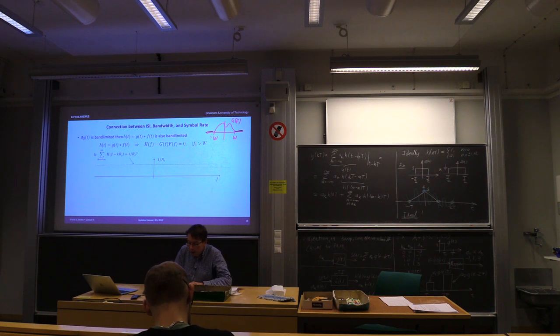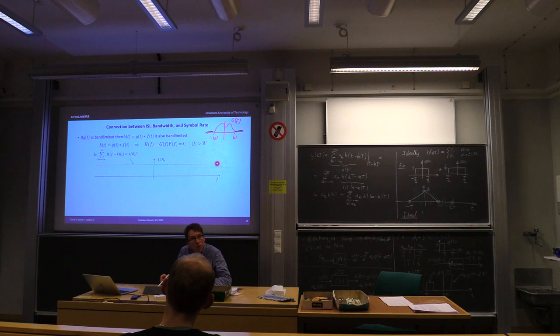So the question we had, to show that H is a Nyquist pulse, is to see whether it fulfills this requirement. If we take H and we repeat that, we form this sum, it should form a constant. So it should be a constant as a function of f. This line here is this constant. So what we want to do is to plot H, put that out and add it together and see whether it adds up to 1. If it adds up to 1, it's a Nyquist pulse. If it doesn't add up to 1, it's not a Nyquist pulse.